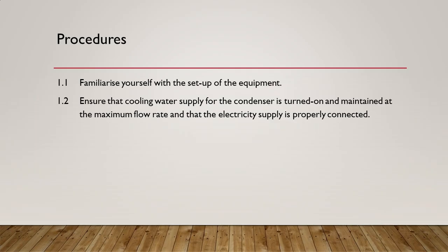In Stage 1, students should familiarize with the setup of the equipment first. Before switching on the power, please ensure that the cooling water supply for the condenser is turned on and maintained at the maximum flow rate. Also, please check if the electricity is properly connected.